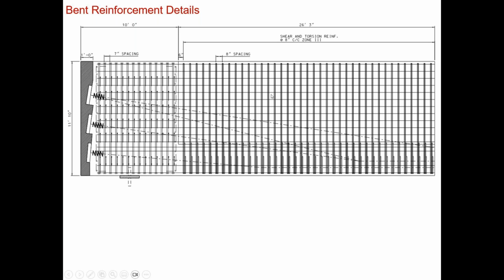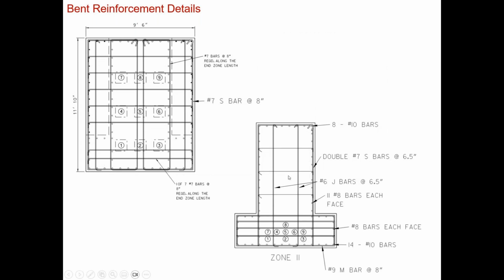Of course, along the inverted T section, you end up with all types of steel for shear, torsion, hanger reinforcement, all added up together, stacked in here, and the edge for shear friction and flexural reinforcement. So that's very typical in these types of bends. That's why it's very critical to find the tendon profile and move out the tendons inside the section.